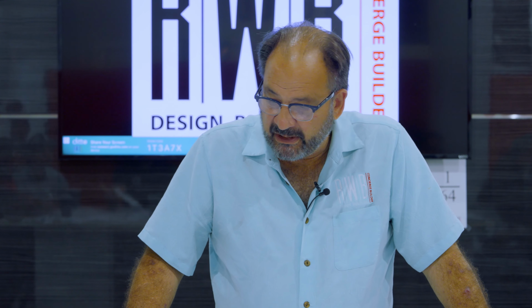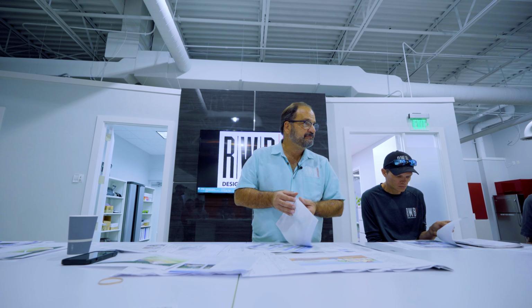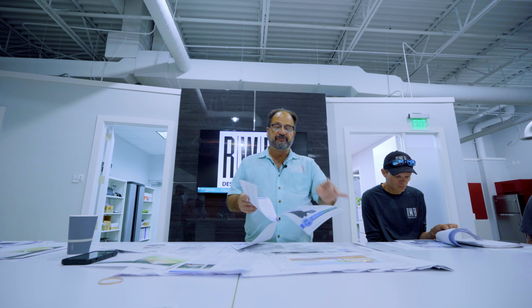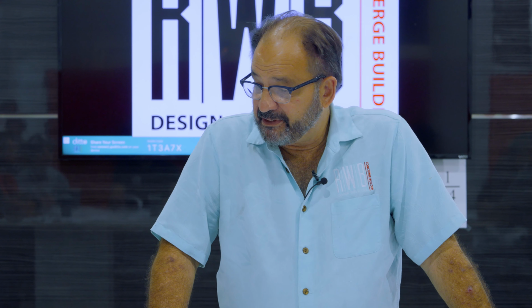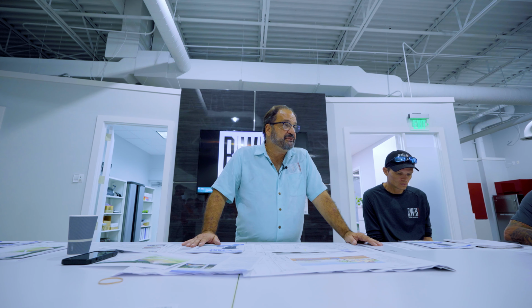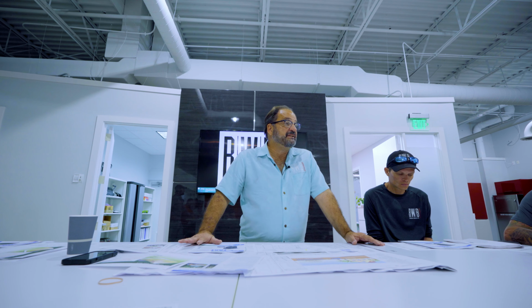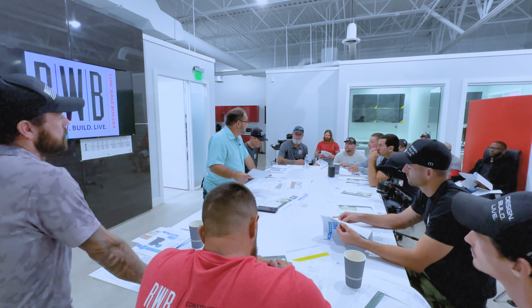One of the things that we do as a company is if you see these tanks within this system, it's our practice to run a sewer line from these tanks to the street whenever we do a job. Because in the future, if the town decides we're going to put a sewer line in, at that point, you can take the line that you've run from the tank to the street, and you can make this a pump station instead of a septic system. So you can tie into your sewer by means of changing the guts of this system, okay?